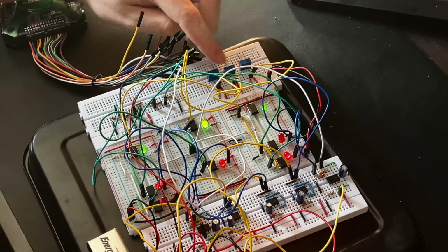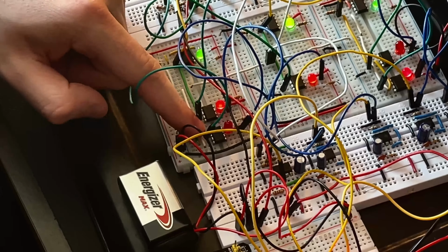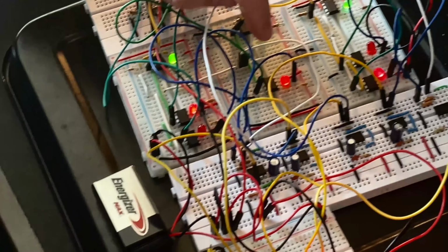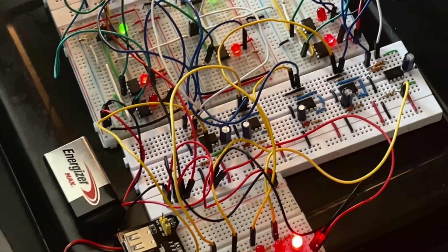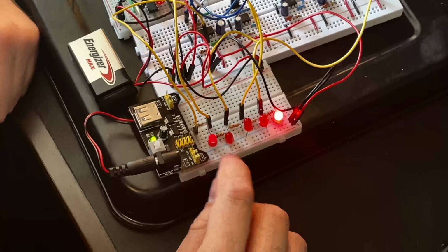So we take the pressure sensor, we can follow it here, indication LED, and there are 2 comparators for min and max. The max comparator runs to a monostable multivibrator, and the min circuit runs to another integrator. These are attached to these 2 LEDs.